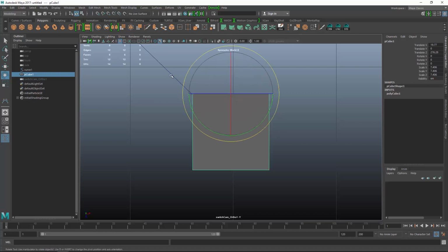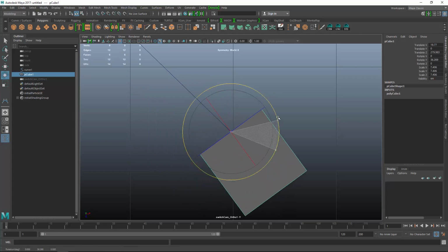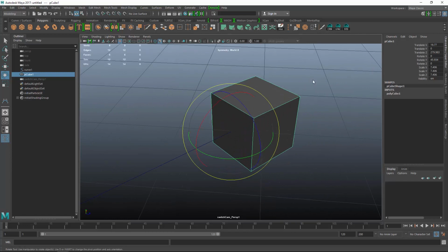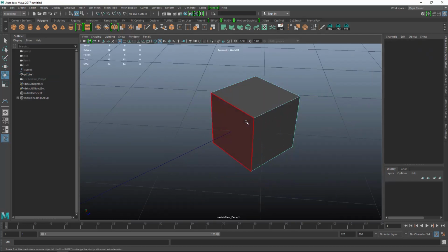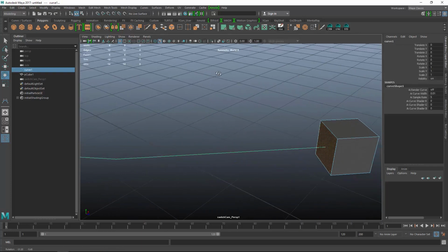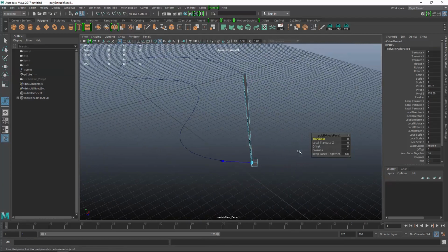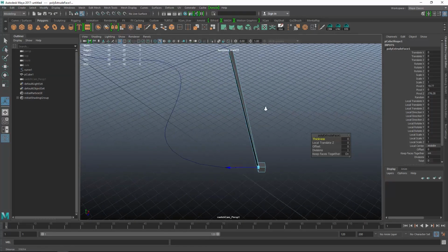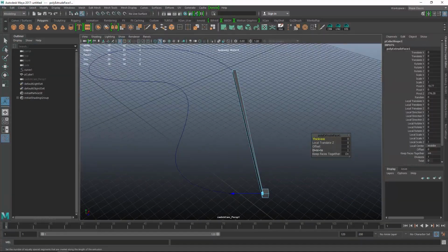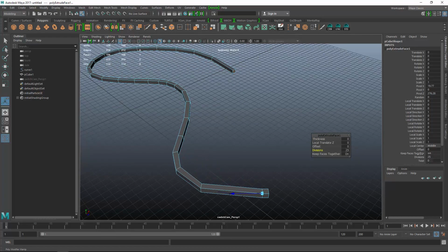and now let's actually curve snap again, and I'll just rotate this a bit so it's kind of even with the curve. And now what I can do is grab this face and the curve and hit extrude. And you can see that it's kind of just made one long extrusion that goes to the end of the curve. But if I add divisions, you can see it start to take the form of the curve.